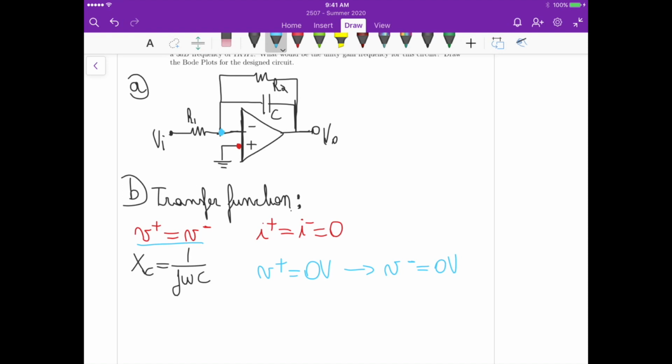So in this analysis we have a current flowing in this direction here, we have another current here, and we have another current here, right? So the first current, we can derive it as V minus Vi divided by R1, plus the second current, or the sum of the two currents, right? That is just V minus, because remember this reactance XC here is in parallel with R2.